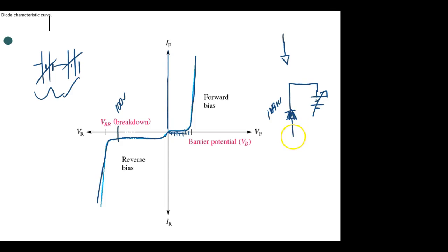And then we're going to come down here and use a 10 gigaohm resistor. Because if I don't protect this thing, it would break over and burn up, right? And so this is going to be a 10 gigaohm resistor, which is basically an open, but it's there. And we're going to take our voltmeter and put it in parallel with it.